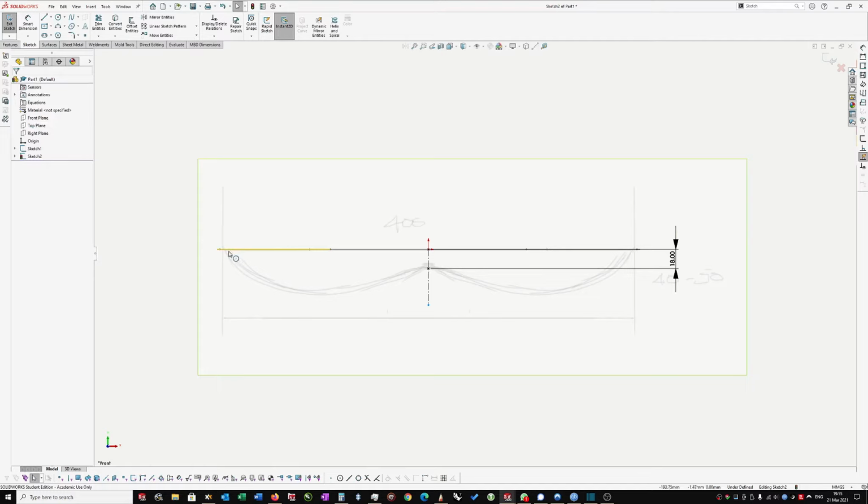And so now I can put in this kind of double dip shape. And for that, I'm going to use the style spline, not the ordinary spline, but the style one. Yours will default to Bezier, but they're all Bezier. Sorry, the first one's Bezier, the other ones are B splines, with that degree. We talked about the degree influence in the last lecture.